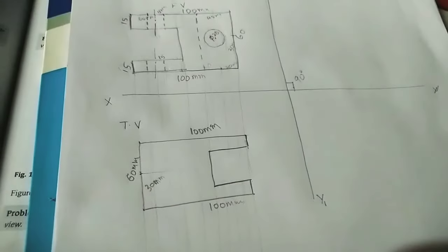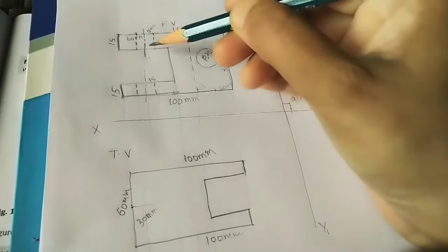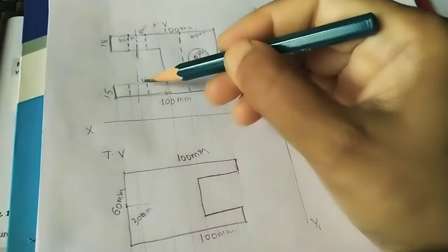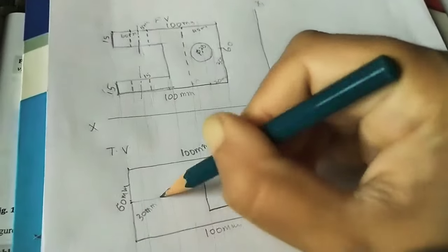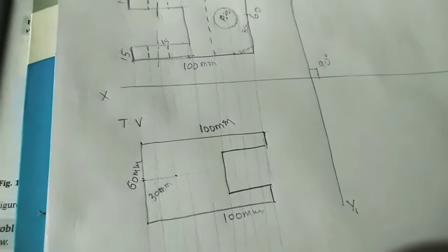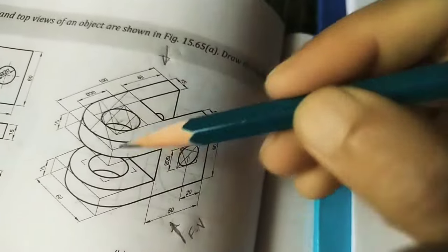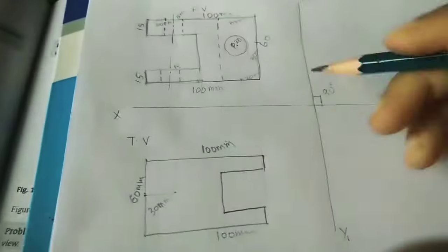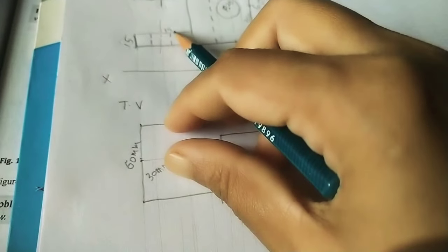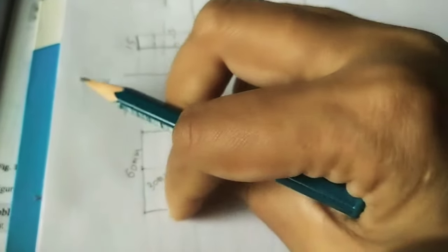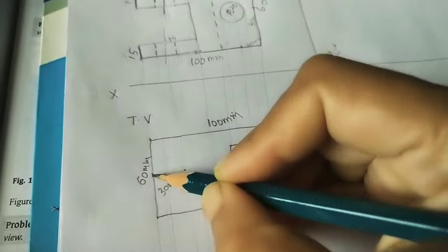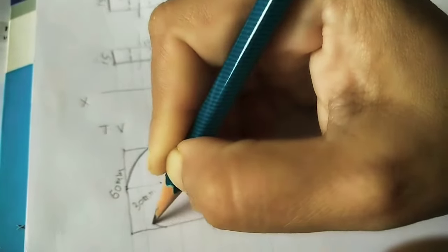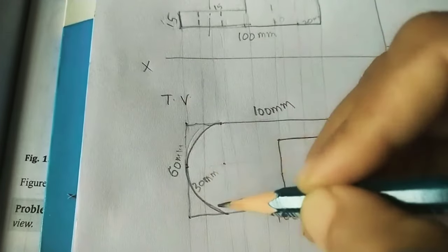Now after that, here take the axis, wherever axis is there. This is the axis projectile line. Take this is the center. Now after getting the center of this, here we can see this semicircle. By using the compass, take this as a radius, do one semicircle. Like this.